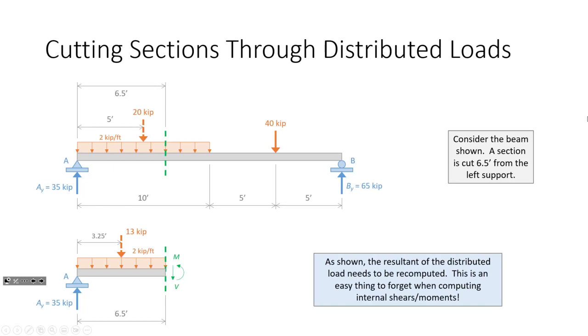When we do this, we are idealizing this as a concentrated load simply to make computing the support reactions easier. Like we turned this into a 20 kip concentrated load just to make figuring these two easy on us. But that's not what's really going on in the beam. If I had 200 pounds to put on this table, what's worse, spreading it out over the length or lumping it right in the middle? Lumping it right in the middle. And so if you just carry this down, you're not correctly representing the internal response inside the beam.